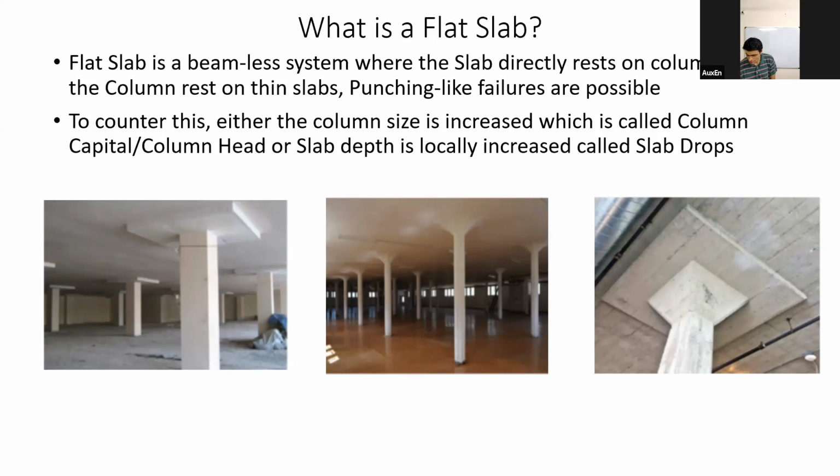Now, if you see this demonstration that I'm trying to show you, I have the slab, and earlier I was using this pen, and I am representing it as a column right now. So the slab was getting punched through by this column. Now, instead of this pen, if I use this as my column, and if I try to punch it through, you will find that I am facing a certain difficulty.